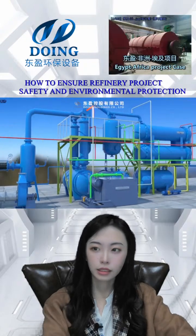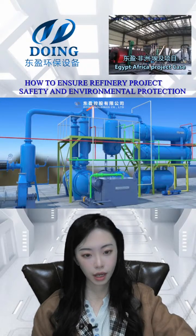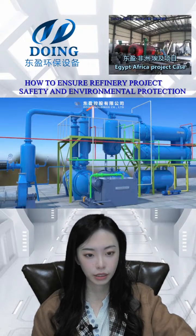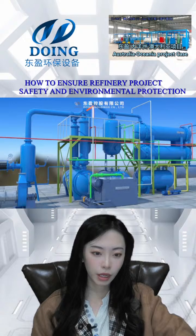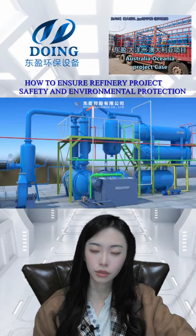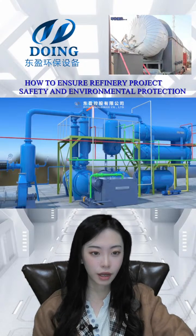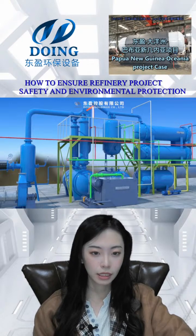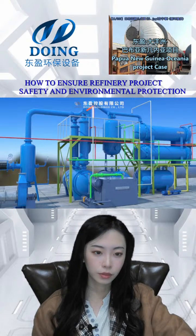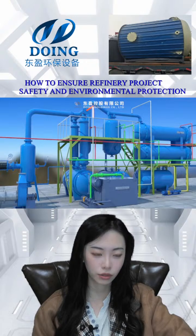And this is the vacuum device. It takes half an hour to an hour to pump out the residual oil gas in the reactor. It will pump it into the horizontal condensers to be condensed into oil. So it has several effects. The first is a safety device. If the concentration of the residual oil gas is very high, it will be dangerous for the oil gas to contact with the air when the reactor door is opened.